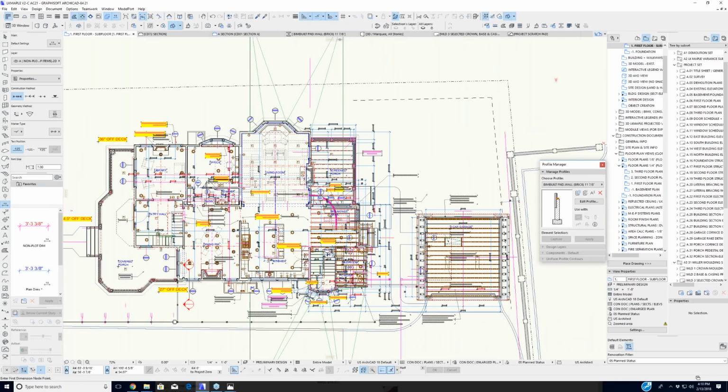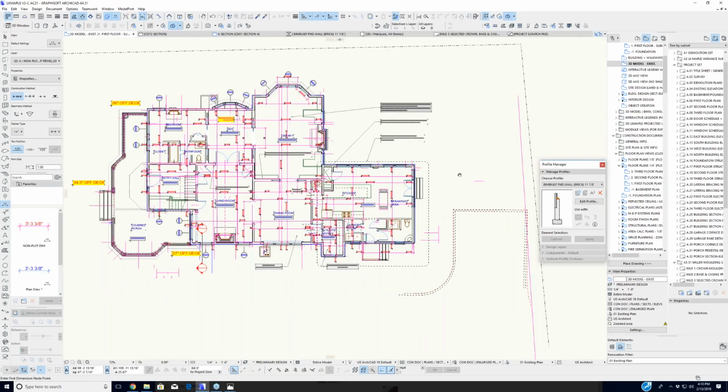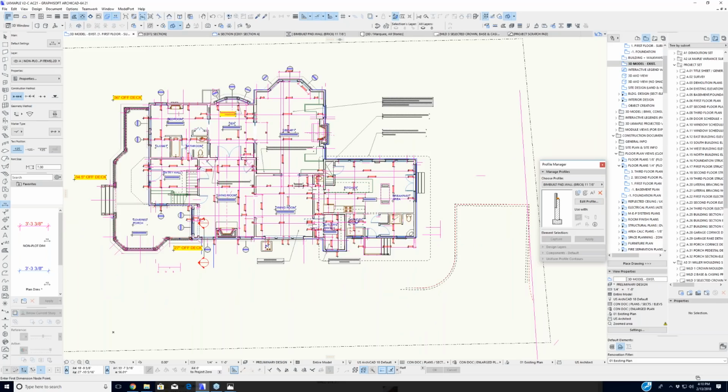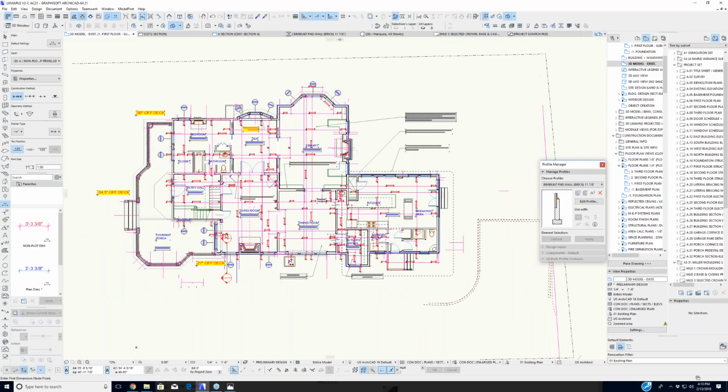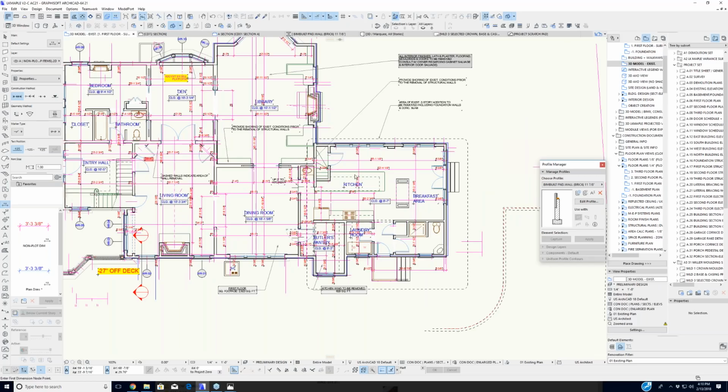Yeah. So in other words, if I click on 3D model existing, now that's 3D model existing everything. Anything that's going to show up three-dimensionally is what would have been modeled. And then that will also be part of a demo plan. But as far as design goes, yeah, I'll work with this right now as a trace reference, and that will be underneath my new floor, and I can start coming out here and thinking, well, where is this porch? Where does the new kitchen come? Okay. So, but you are using the renovation filters.